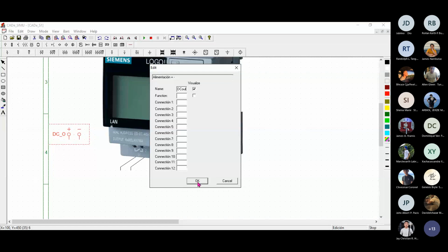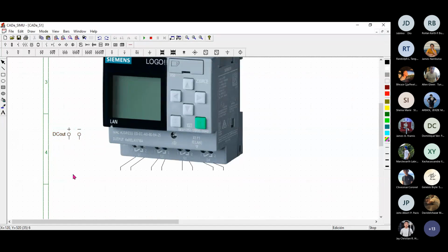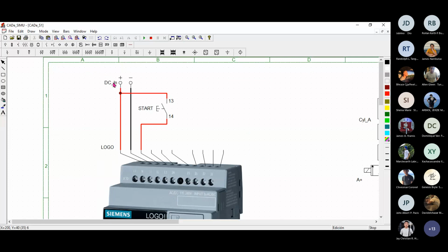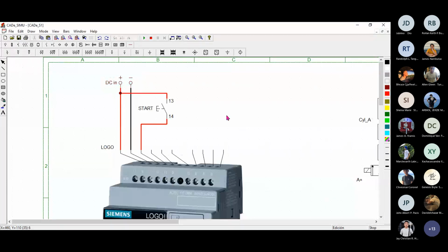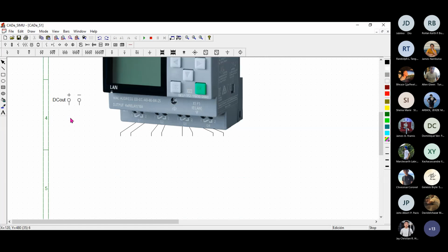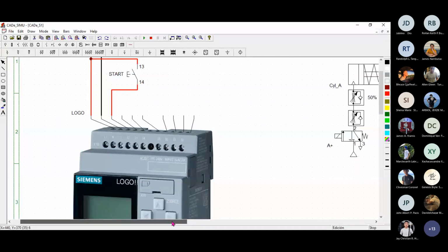And then at the upper portion, basically you can have DC input, DC space input or IN, and then at the bottom part that's DC out. Okay, so how do we connect the outputs, by the way? First we have to identify what the load is. As I mentioned, that's the solenoid coil, or the coil of the solenoid valve. Okay, so where can we find the coil of the solenoid valve?